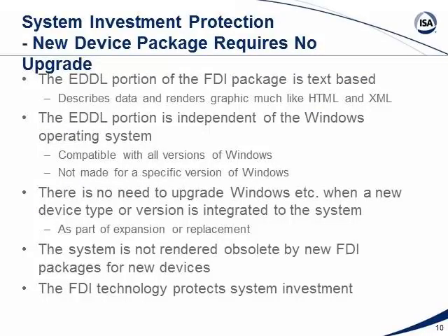A new device package requires no upgrade. The EDDL portion of the FDI package is text-based, describes data and renders graphics much like an XML file. But XML just provides a syntax, while here the EDDL provides semantics.